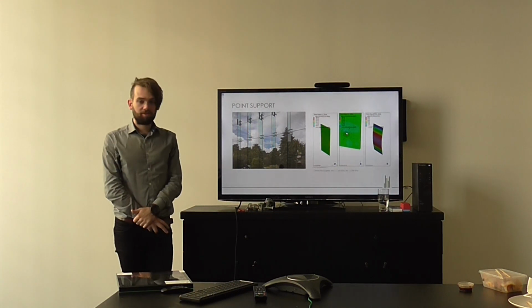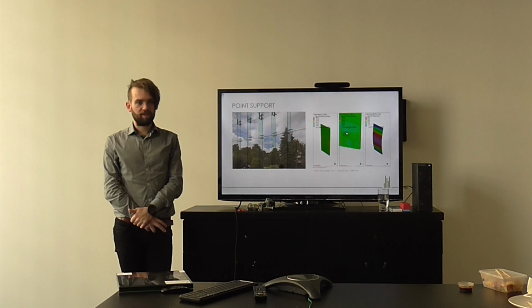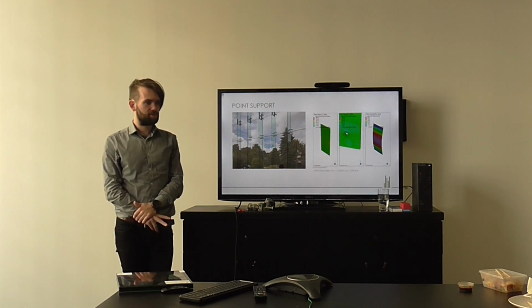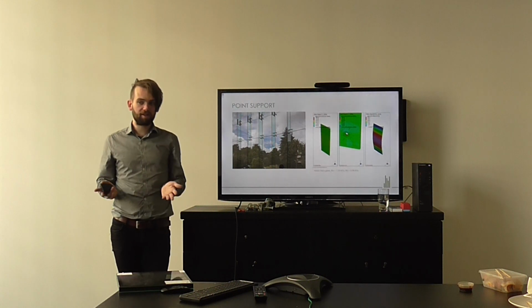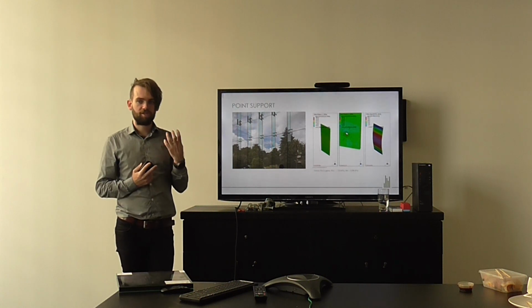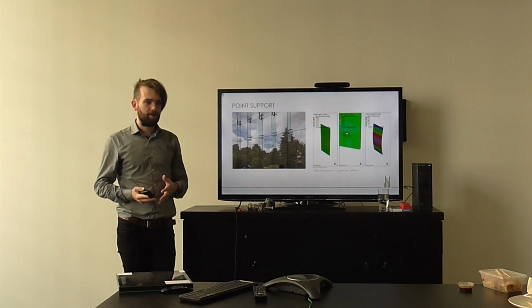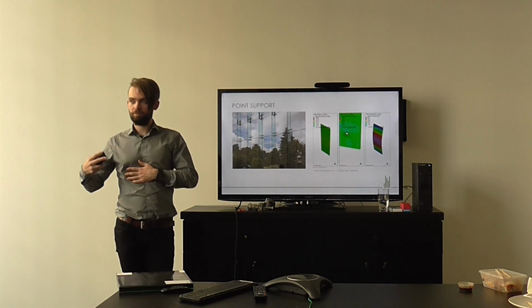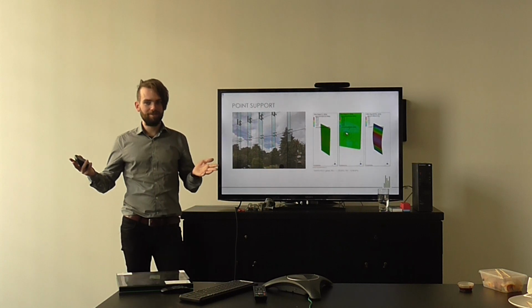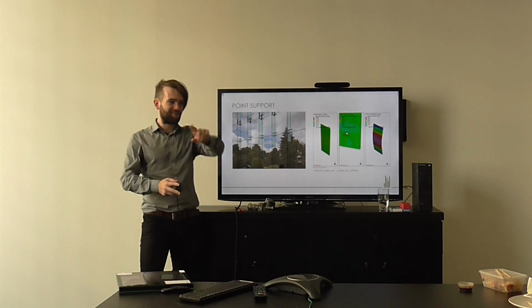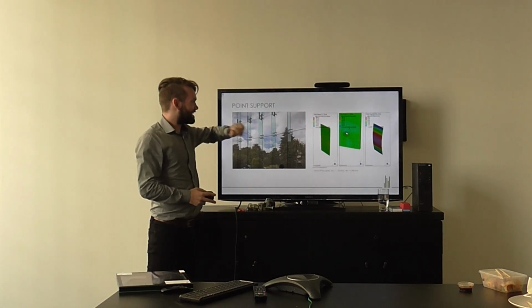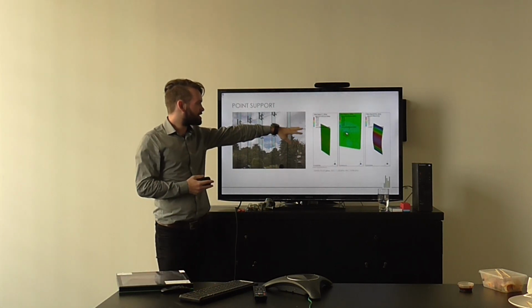That is quite common with point fitting glass, and it's why, as a general rule of thumb, it should almost always be toughened glass, because you get very high stress concentrations around the hole, and in order to deal with that, you need the strength which comes from the toughened glass, which we previously touched on. How many times stronger is it than annealed glass? You're not allowed to answer. And as you see in the displacement, it's about 30 mil.